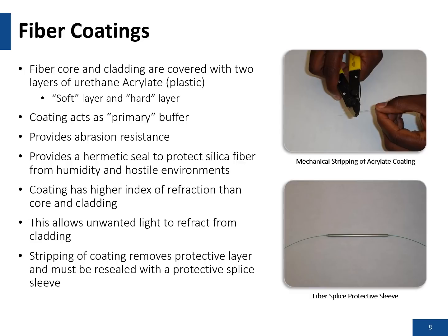The coating has a higher index of refraction than the core and the cladding. And basically what this allows for is once the light has escaped from the core into the cladding, it allows the light to not stay trapped inside the cladding itself. It allows it to escape.